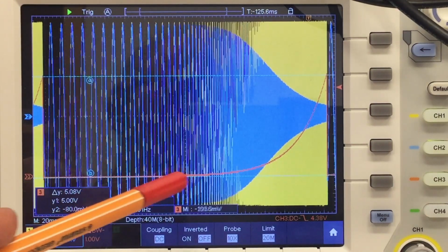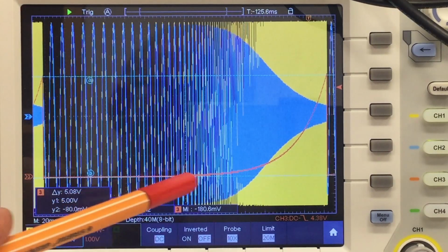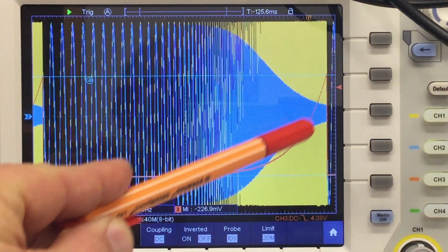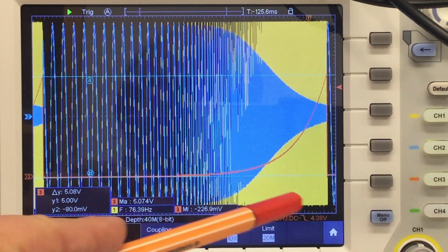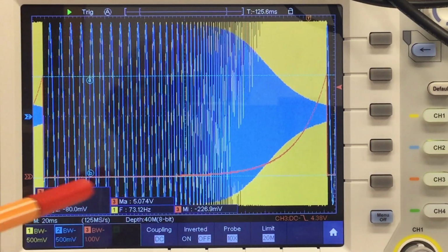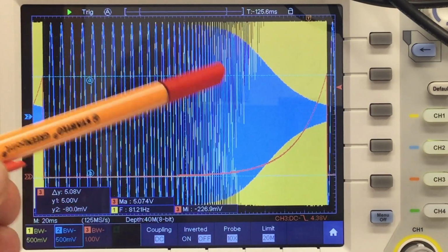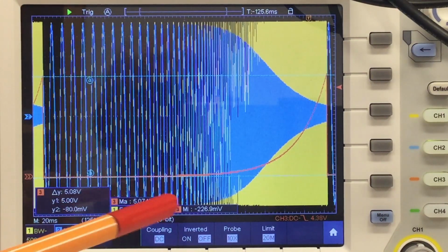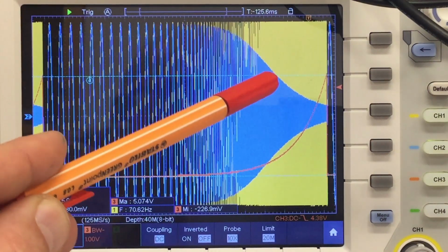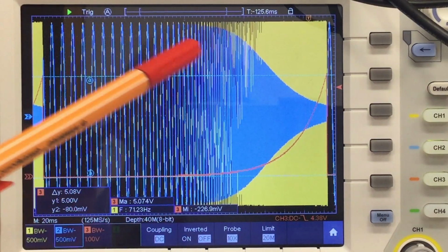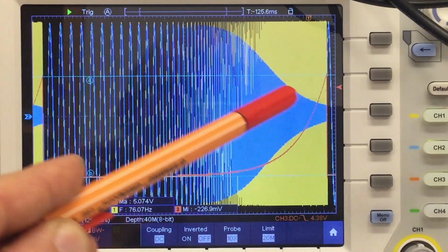So that's our input signal to the VCO, which is now an exponential curve, which it should be when we want a logarithmic frequency scale at the bottom. And it's down to 3.5 hertz, I think. That's the lowest I can get without losing my trigger. And we have our output signal in blue from our DUT, that is our RC low pass. And you see, it's almost linear here in that region.